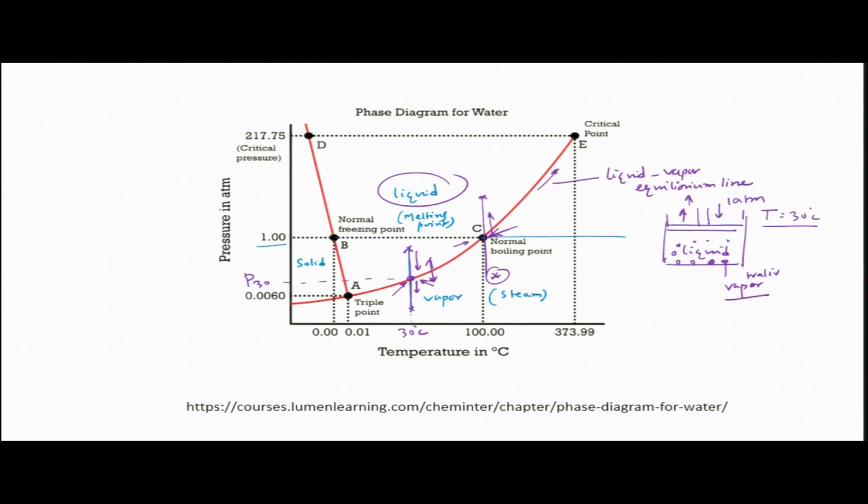Fine. Now, let us say the pressure reduces and vapor forms. Now, when pressure increases, this vapor will collapse, and let us see, if this is the vapor, it does not collapse like this, it collapses like this, it becomes like this, and then there is a water jet.